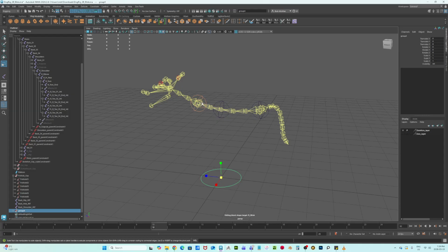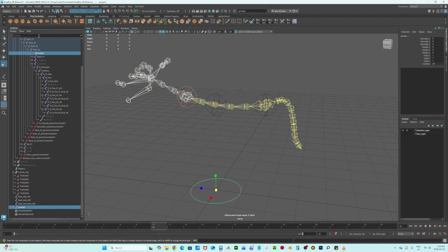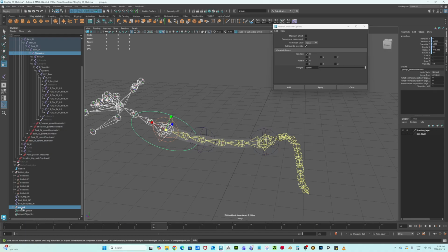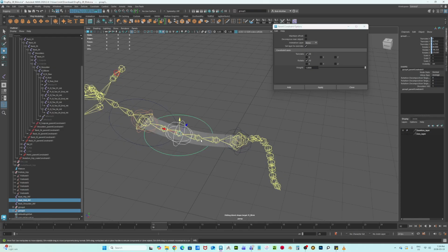Okay, I'm going to take this joint right here and I'll grab the group and I'm going to put on, let's go to constrain parent, and let's see what parent's got, maintain offset. I'm going to go in, turn that off, and I'll hit apply, pops it up there. I'll take this same group and I'll make a duplicate. The duplicate, I'm going to go over and grab this joint. Now this is the wrong order, so I could switch that. I can go to Object and make it so the group is selected last. I just went up there and did that. And I'm going to hit apply, and now we got constrained and oriented over there.